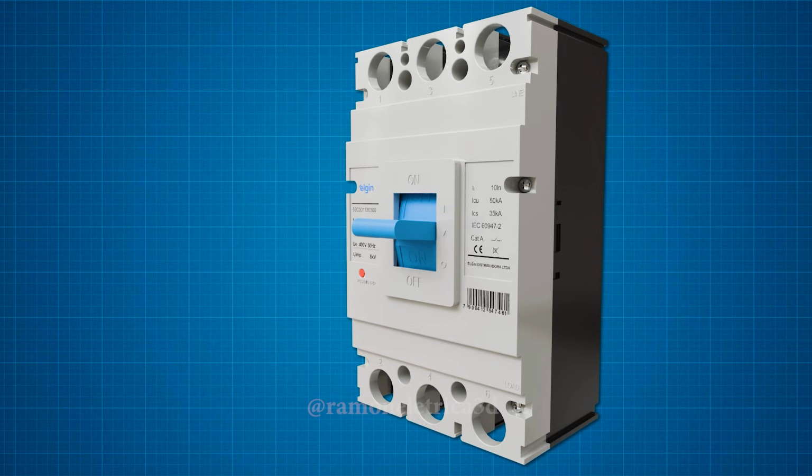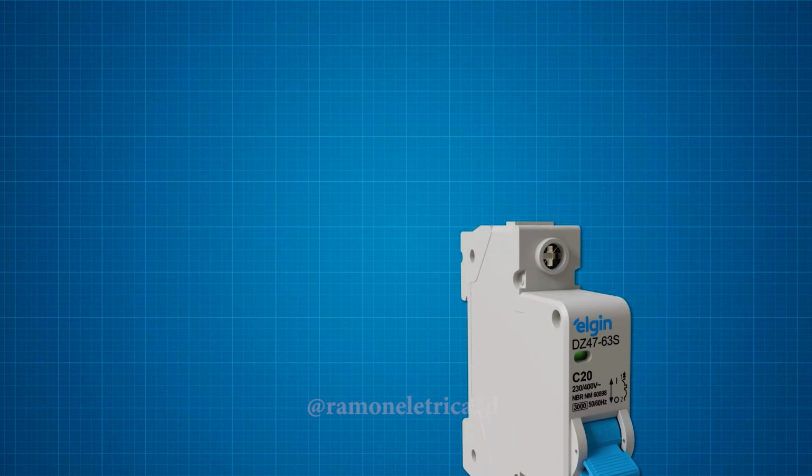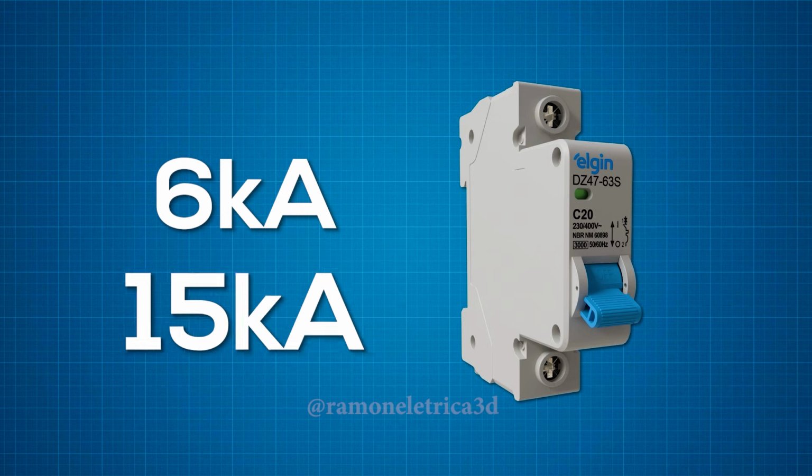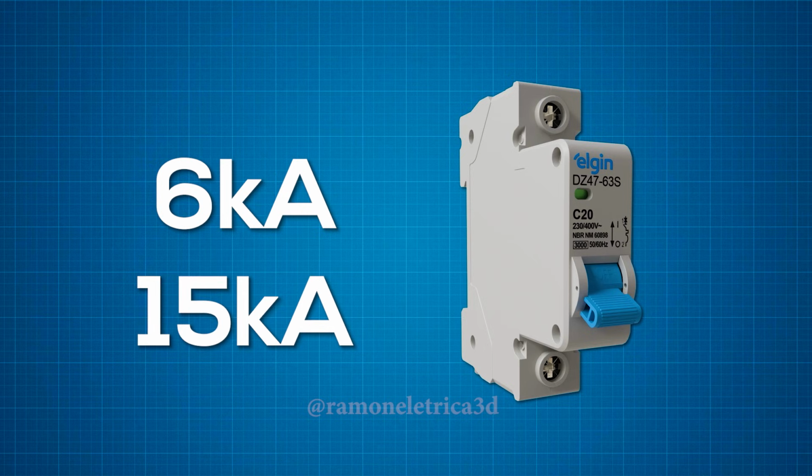Another important point is the short circuit current. Let's imagine you have an MCB with a 6 kiloamp short circuit rating, but your installation has a prospective short circuit current of 15 kiloamps. In this case, even if the MCB manages to interrupt the circuit, it may explode or suffer severe damage because it was not designed to withstand that level of short circuit current. In this scenario, an MCCB must be used.